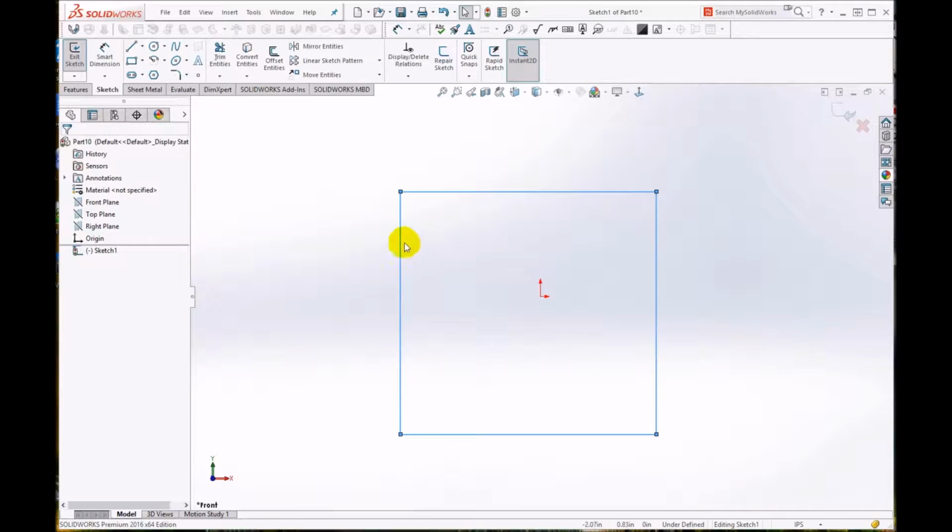It has a vertical size, which would be between these two lines, and a horizontal width, which would be between these two lines, the two vertical lines. So let me go ahead and click on Smart Dimension. I'll show you a shorthand in a moment. And now I'm in dimensioning mode. Notice how the cursor changed appearance. That's your primary and sometimes only clue that you're in dimension mode.